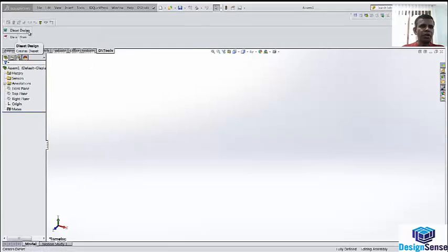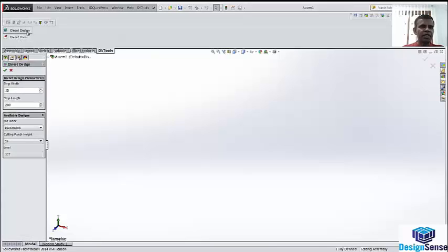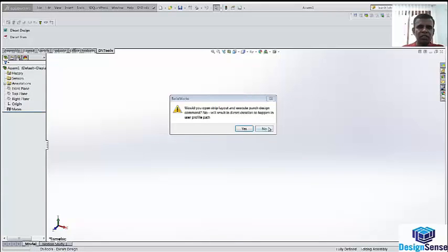I was showing you the double die set, so let me also show you this length. Strip width and length can be edited without reading from the strip. So let me put some numbers here, and let's see what comes up. So for a strip length of 30 by 200, I am given two choices of die sets. Let me pick this and then see what is coming up.